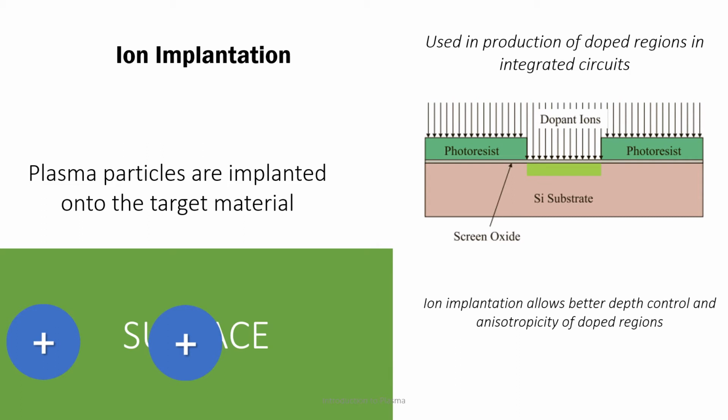We can actually program how deep the ions will go. And it is also more anisotropic than diffusion-based systems. This is especially important since in very, very small devices, we need that much control.